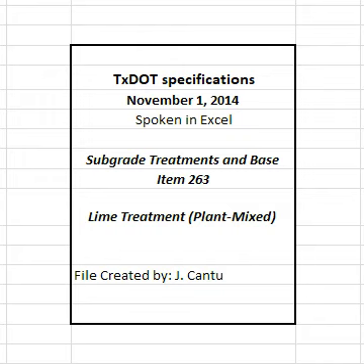The engineer will determine roadway density and moisture content of completed sections in accordance with TxDOT 115E. The engineer may accept the section if no more than one of the 5 most recent density tests is below the specified density and the failing test is no more than 3 pcf below the specified density.